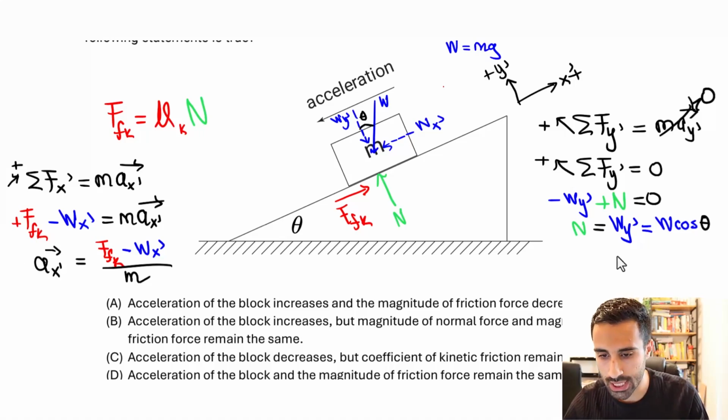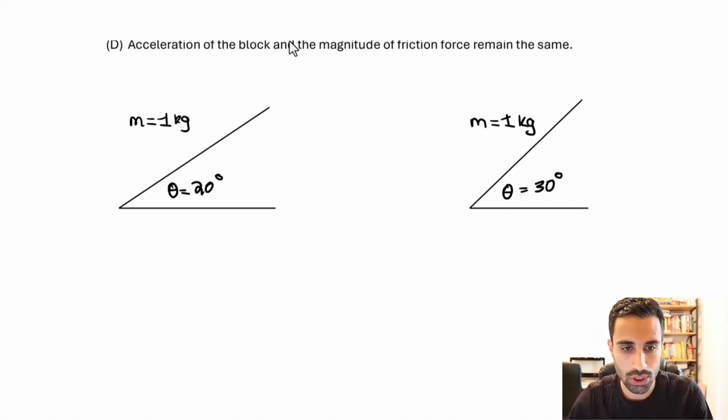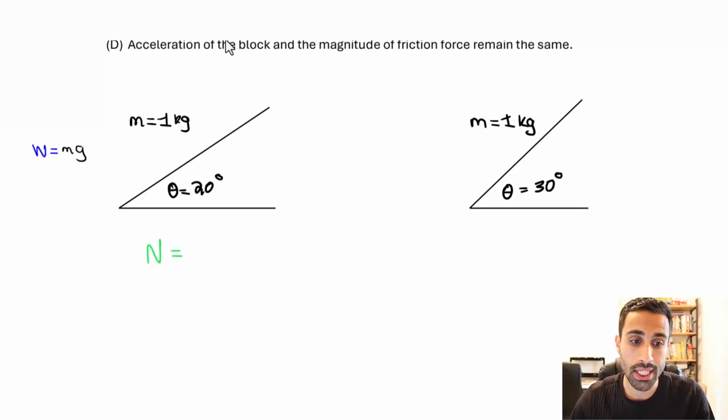Normal force, it says, is weight cosine of theta. So let's do that here. The normal force, we put that in the calculator, and that would be the weight. Note, the weight is mass times gravity. So I'm going to do that on the side, mass times gravity. In this case, we can use either SI or US units. Here the weight would be a little complicated in US units, it would be 1 slug. So let's use the easier SI, 1 kilogram.